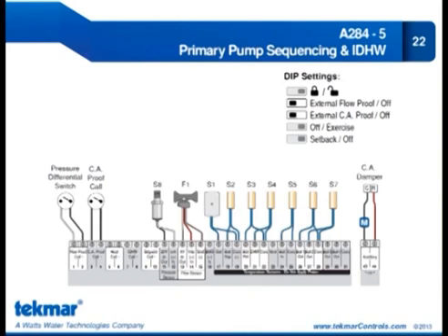Okay, but as far as what the 284 supports, it's basically, again, Modbus, which uses RS-485, and we support two types, whether it's RTU, which means Remote Terminal Unit, or it's the ASCII. And then on the BACnet side, of course, it's IP. So we support one or the other. You basically select what protocol you want to use. Any questions on that?